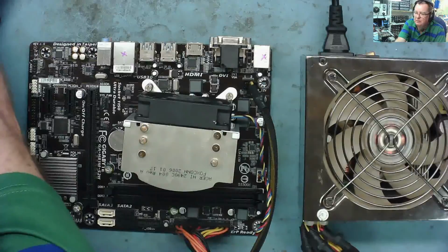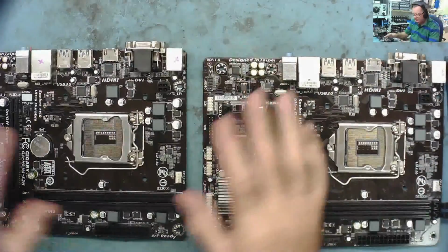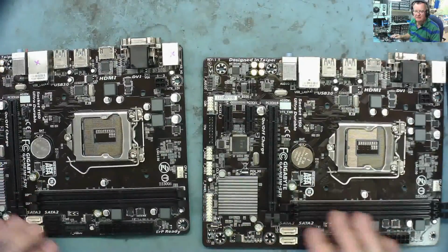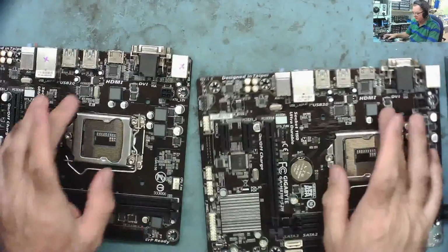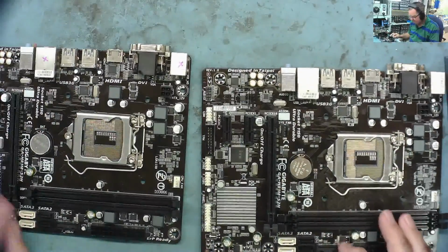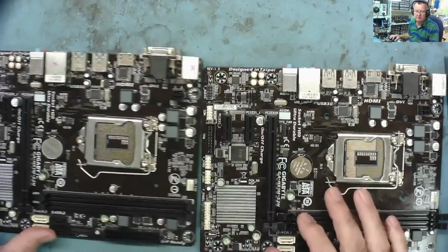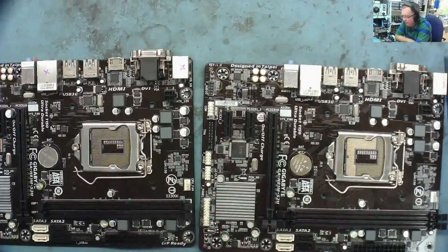Okay, let me have a look. Okay, I've done that. I've checked all of the regulators I can see and all the coils. There's some more down here, to do with the RAM, and there's this one here I don't think I checked before. There's a number of these, either FETs or voltage regulators, LDOs. I've checked them all, there's no difference.